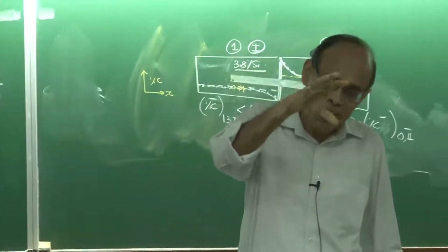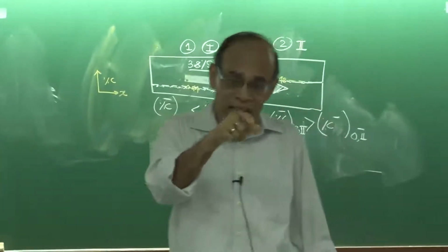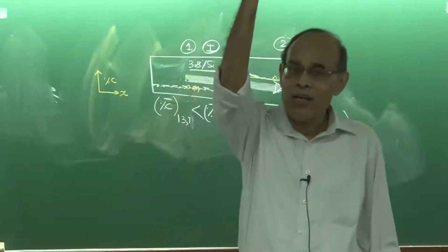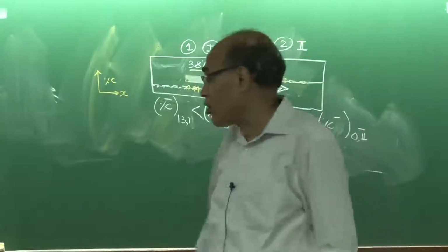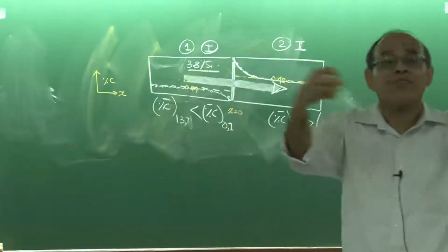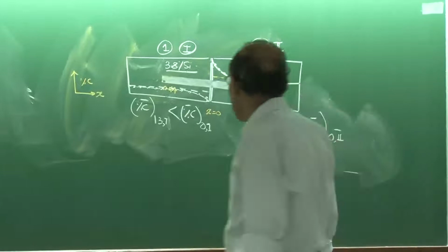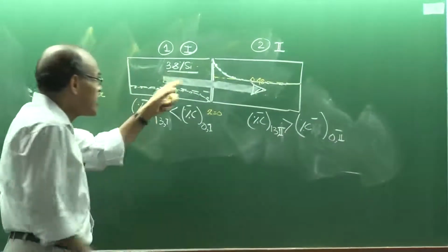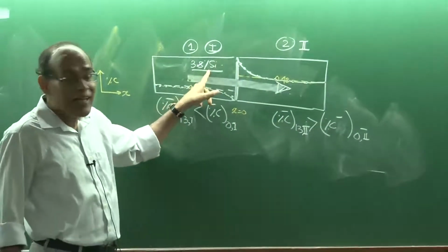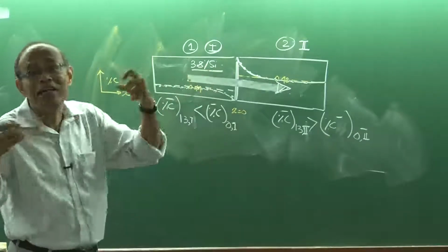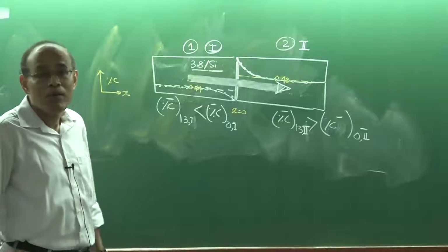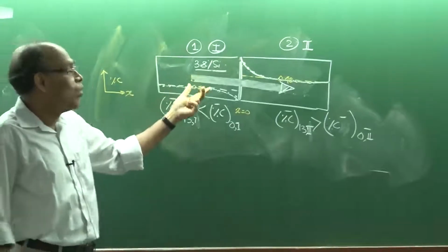So in a two-component system, if you add a third element, that third element can increase the activity of the other constituents or decrease the activity of the other constituents, and it depends on the relative strength of the bond forming between various constituent elements. In this case, silicon is such that the presence of silicon does not allow much iron-carbon bond to form. So you can visualize it.